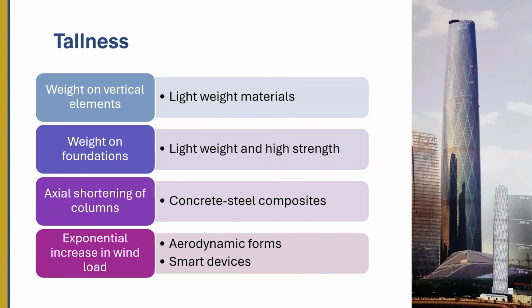Because these issues do not exist in other buildings. First one is weight on vertical elements is a major issue. Like I mentioned to you, it's a challenge because everything just multiplies very quickly and adds up for the foundation until the foundation becomes impossible. Many tall buildings cannot be made because the foundation soil is not good enough.